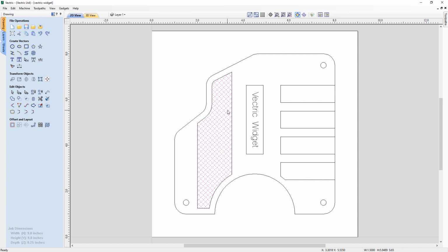In this project, we have used a number of simple tools to create a more complex part, using offsets to create these edges, creating circle vectors in the corners, using fillets to round off sharp edges, using the Polyline tool to create our basic outline to begin with, using the Array tool to create our groups of rectangle vectors here, the Text tool for this text section in the middle here, rotated 90 degrees, and then the Array tool, the Trim tool, and the Scissors tool to create our hatching vectors here, and then clean them up to leave only the parts we want.